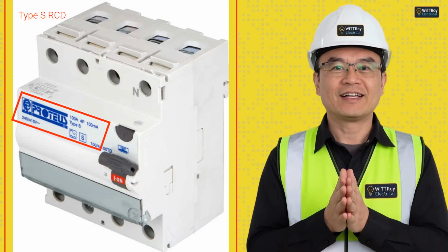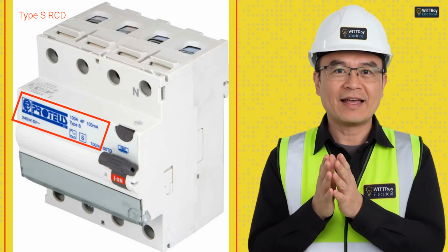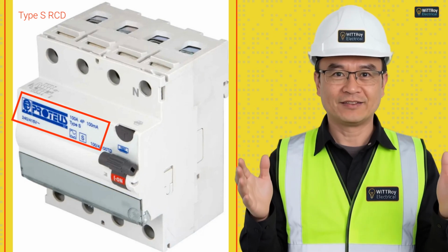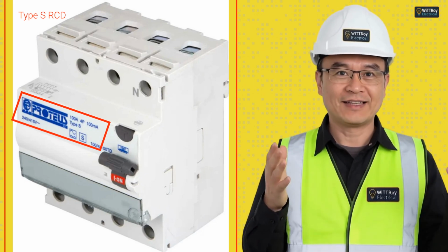Let's look at this device. I can see 100 A 4P and 100 mA. That means it is a 100 amp 4-pole RCD with 100 milliamp earth leakage protection. I can also see type S. Type S means selective or time delay.